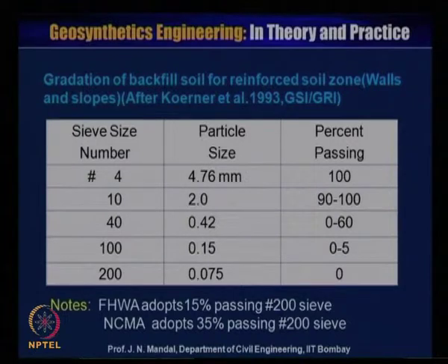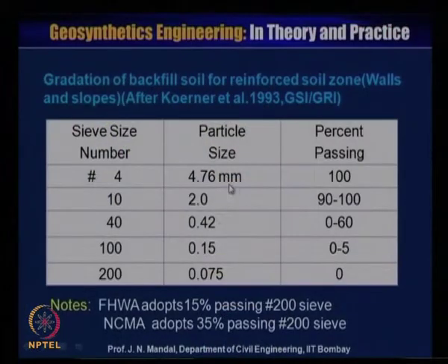This is very, very important because most of the time if we do not select the proper kind of gradation of the soil material, then there is a possibility for the failure. So as per sieve number 4, 10, 16, 40, 100 and 200, the particle size lies between this and percentage of passing will be this.